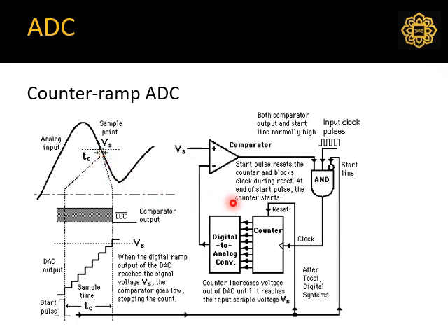So it will have a clock and a timer. That will cause it to increase the counter value digitally. It will turn on and off different switches with the counter. Once the counter is going from lower to higher level, it is converting this digital value to an analog voltage, and it will be compared with your actual set value.